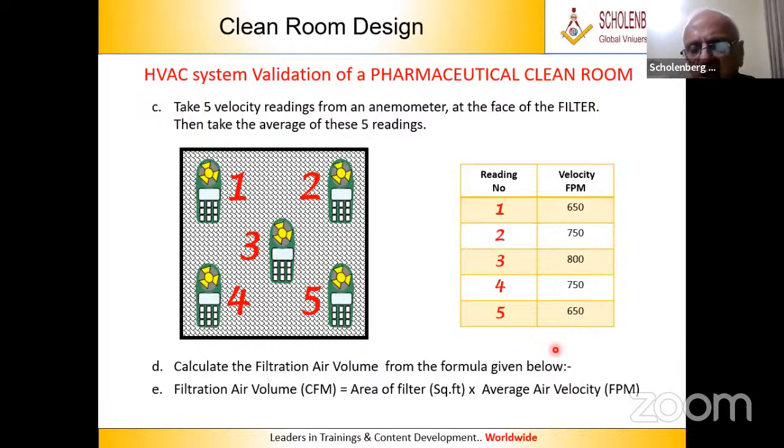They'll be near the standard parameters, slightly different because of the requirement. For example, in wafer manufacturing, very caustic fumes come out, so that has to be exhausted. That rate of exhaust, and accordingly the rate of input, will change the number of air changes.